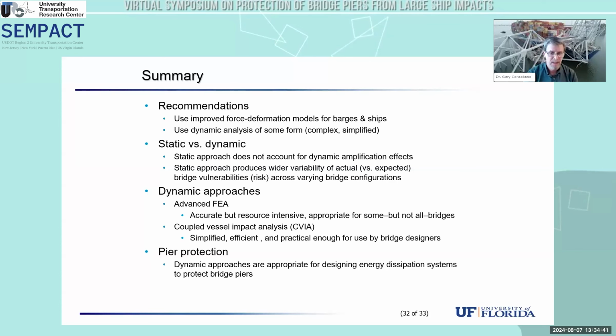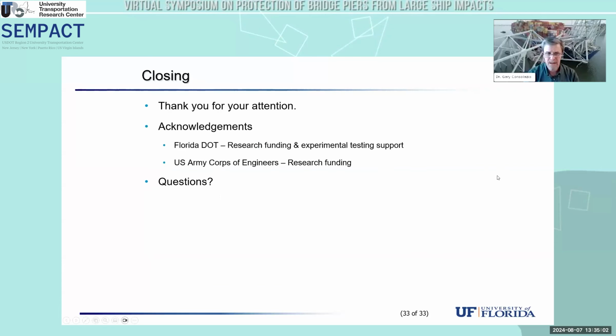And so that's another option. Finally, in terms of pier protection, obviously dynamic approaches are quite appropriate for designing energy dissipation systems that protect either completely or partially bridge piers from impact by either arresting a vessel or reducing its kinetic energy.